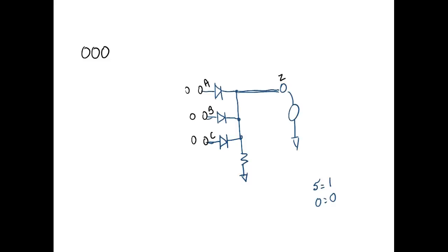So I could put that input on there. 2, 3, 4, 5, 6, and 7. That's all. I can't put any more. 1, 2, 3, 4, 5, 6, 7, 8. So on a digital logic gate, you can tell how many input combinations you have. Just count the number of inputs and raise 2 to that power.